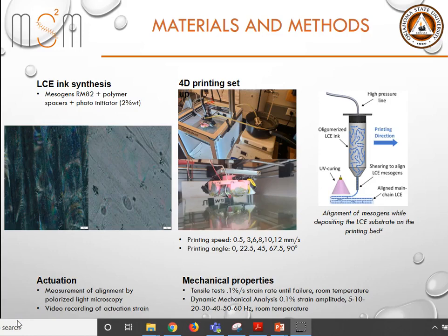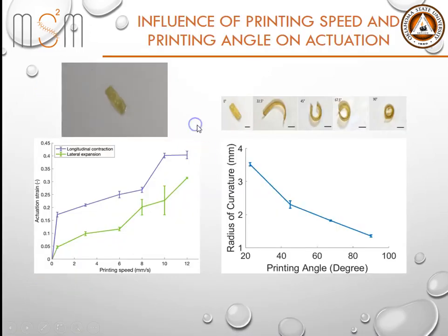To find out the mechanical properties of 4D printed LCEs, we conducted tensile tests at 0.1% strain until failure. We also conducted DMA, or dynamic mechanical analysis, tests at 0.1% strain amplitude and at different frequencies.